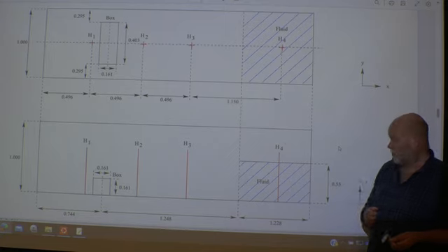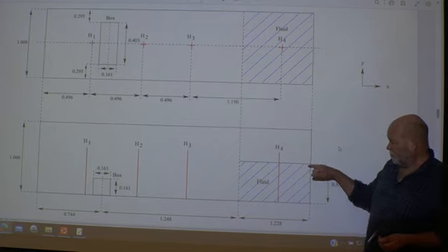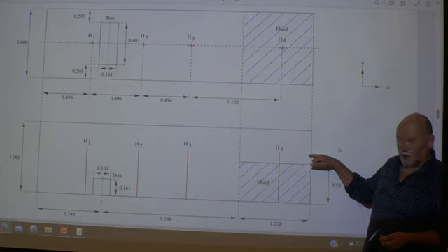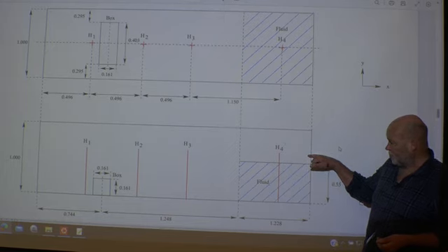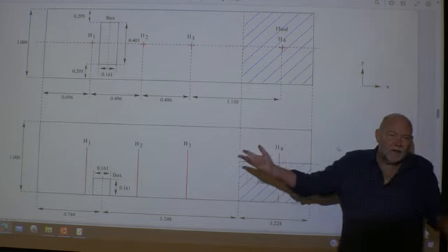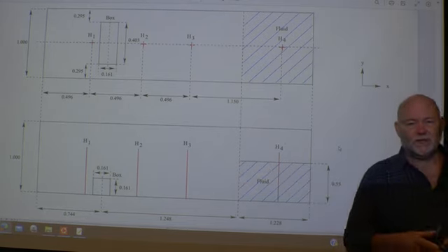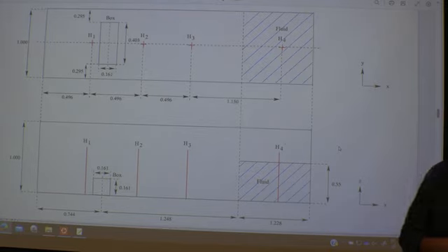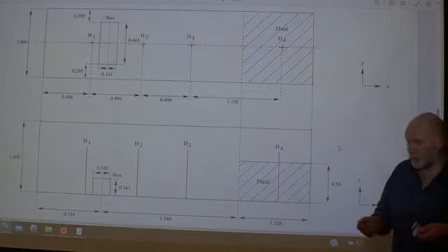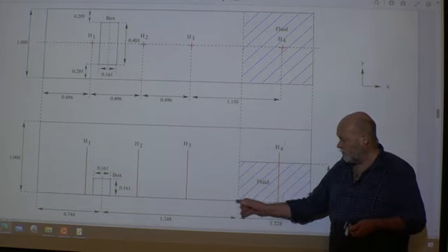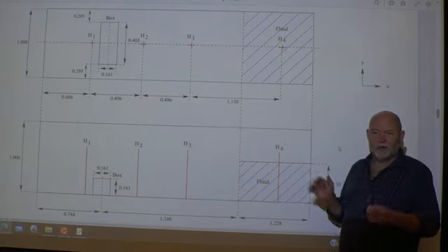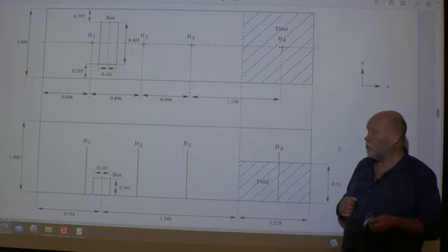That's not good. Especially for the height here. If you have, say, a very coarse mesh, so it will have the height up here or down here, of course you'll have a totally different result. That's not good. So try to make sure when you create 3 different meshes that this initial volume is roughly the same. That's a good point, actually.